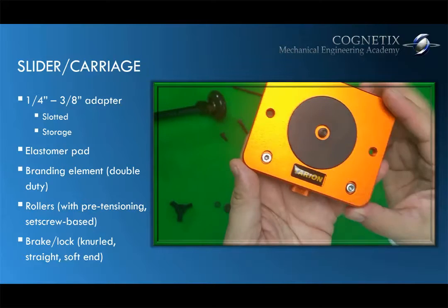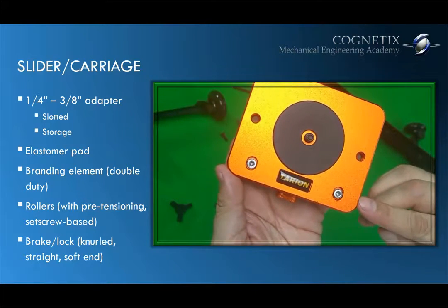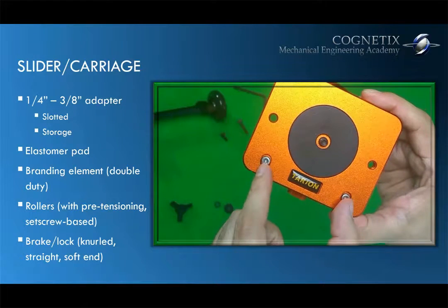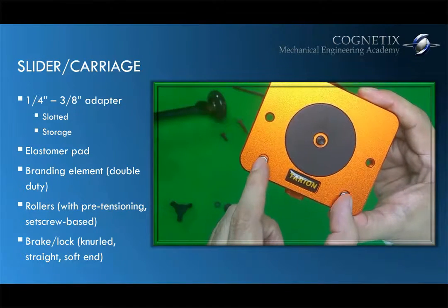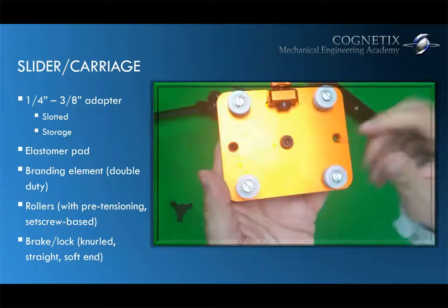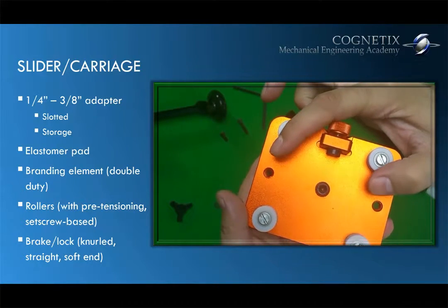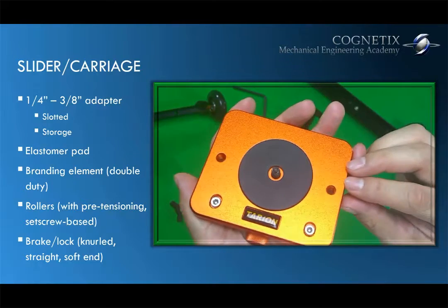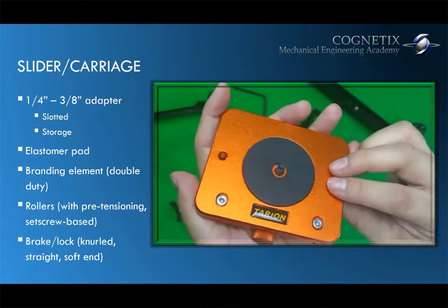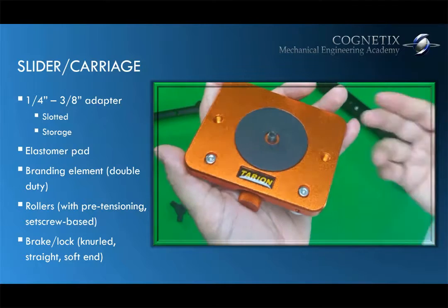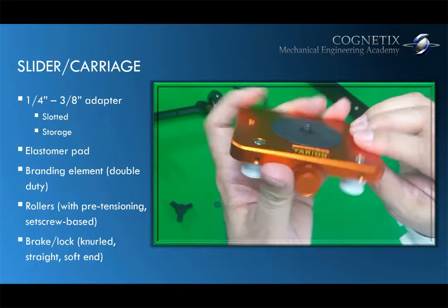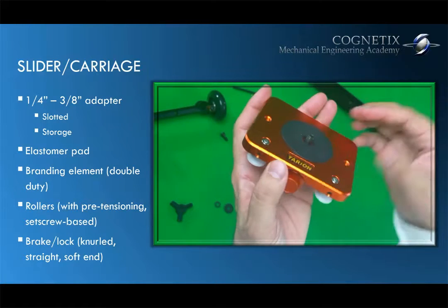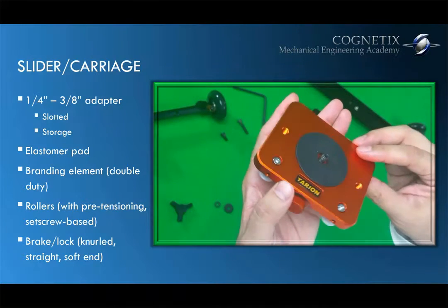The design has adjustability. When they assemble the rail, during assembly, they tighten the axis, they bring the axis closer, and they bring the rollers in contact with the rail, and then they tighten the rollers into position. Very nicely done. This kind of thing is done in machine design, mechanism design, and of course, product design. Okay, it's another one of the topics that we cover in the academy.